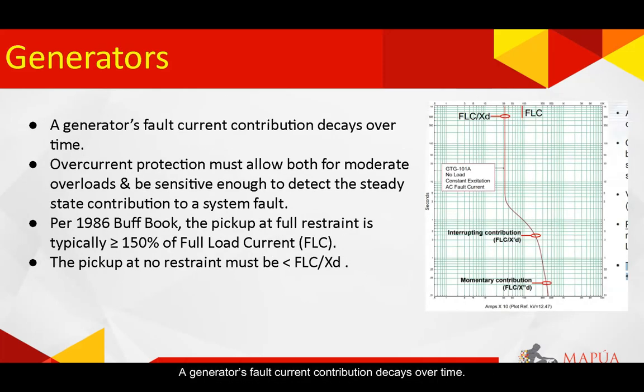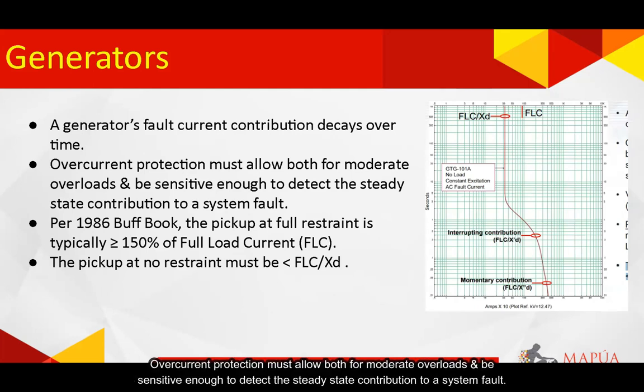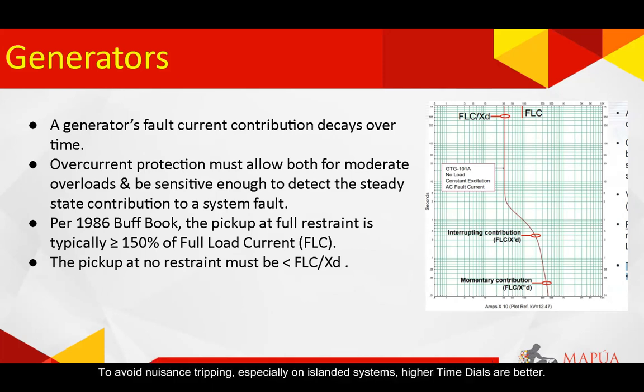A generator's fault current contribution decays over time. Overcurrent protection must allow both for moderate overloads and be sensitive enough to detect the steady state contribution to a system fault. To avoid nuisance tripping, especially on islanded systems, higher time dials are better.